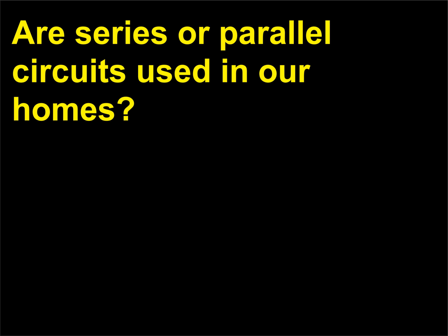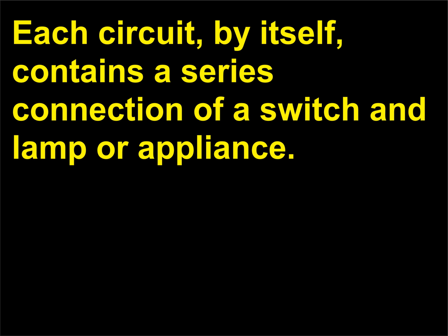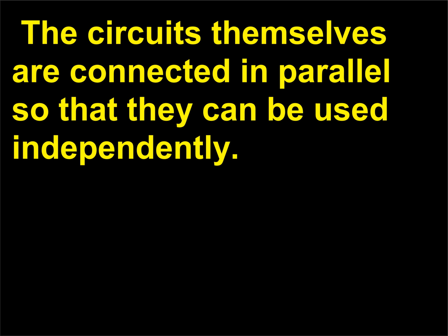Are series or parallel circuits used in our homes? Each circuit, by itself, contains a series connection of a switch and lamp or appliance. The circuits themselves are connected in parallel so that they can be used independently.